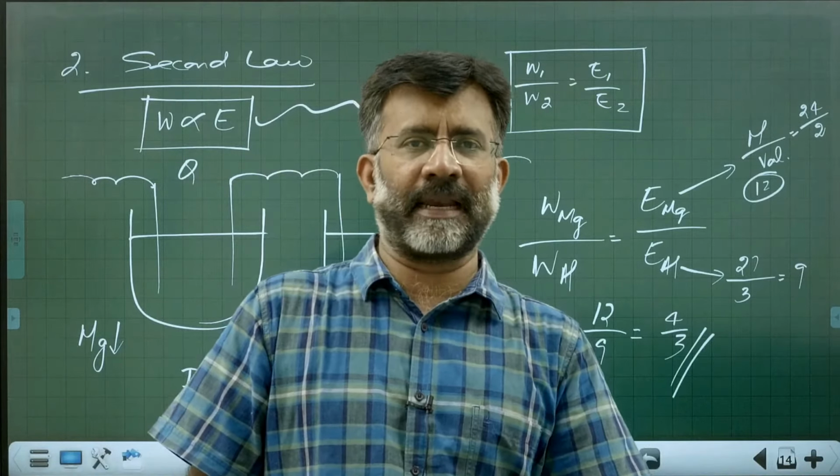And you see, this area will be acting as an anode, and this area will be acting as a cathode. At the anode, oxidation takes place, and iron is converted to Fe2+. These electrons are carried away to the other side, where they interact with oxygen and H+, and it is converted to water. Subsequently, Fe2+ will be converted to Fe3+, and finally with oxygen, it is converted to rust. This is rust, Fe2O3, ferric oxide. Hydrated ferric oxide is called rust.